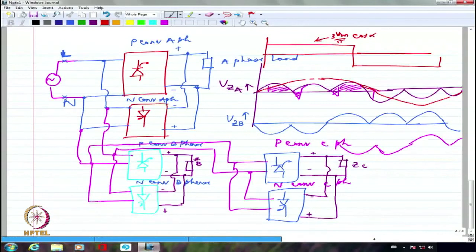SCR is also slow and they can handle very large power. So they all match very nicely. Thyristor based converters will work slowly. They are much slower than IGBT or MOSFET or any of them. And they can handle single-handedly almost 30 megawatts of power without any difficulty. Because of which, for high power drives, we generally tend to prefer thyristors.